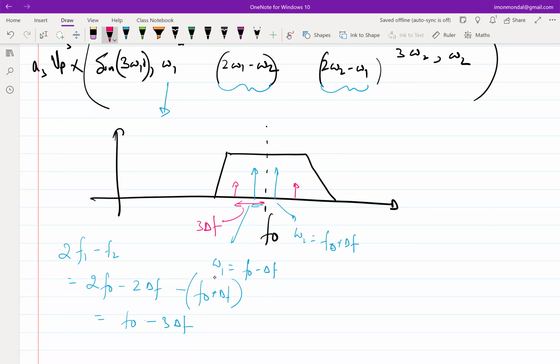So there is a way, and by the way, better the amplifier, the lower will be this red delta, or the higher will be the difference between the heights of the intended signal and the unintended signal, right? And worse the amplifier, smaller will be that difference for the same amount of input amplitude, right?